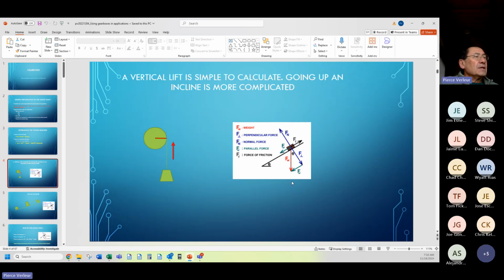And these are the forces that are associated with an incline. The hoist is a special case where theta, the angle, is actually 90 degrees. Not inclined, but vertical. And of course, the friction vectors that would be used on an incline are zero because you have no friction other than windage, which is completely insignificant in lifting the load.